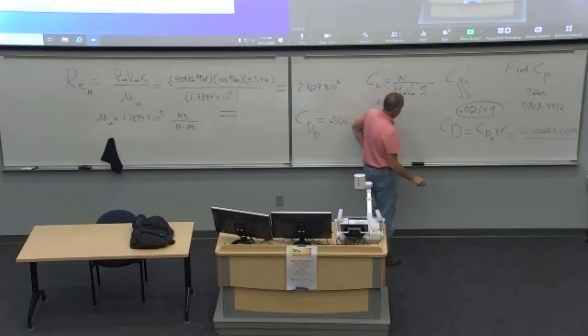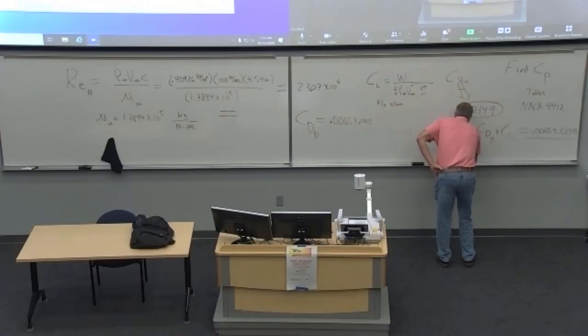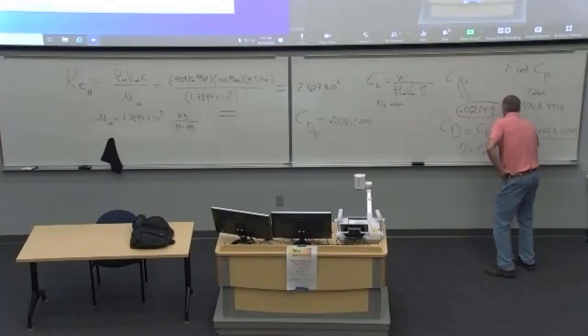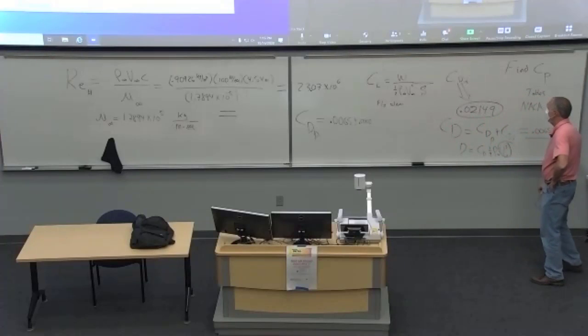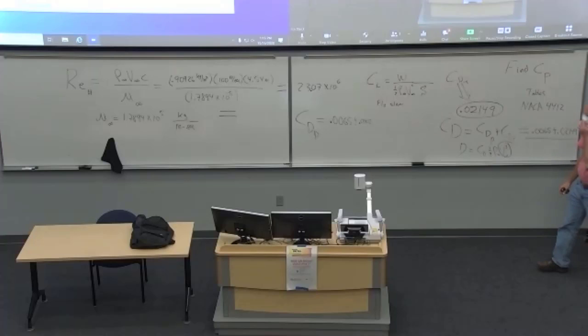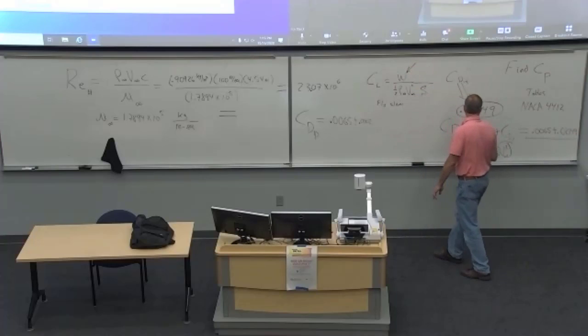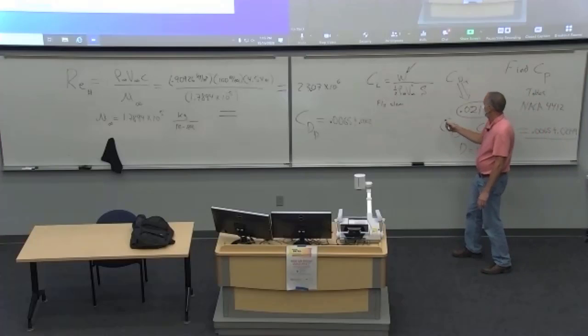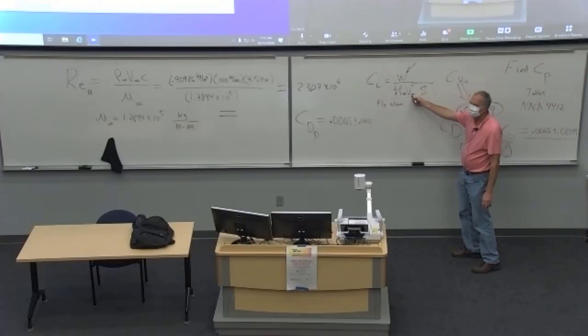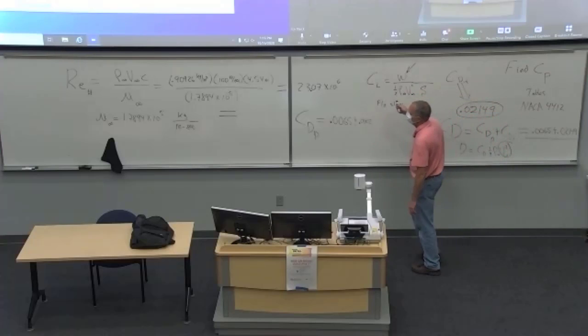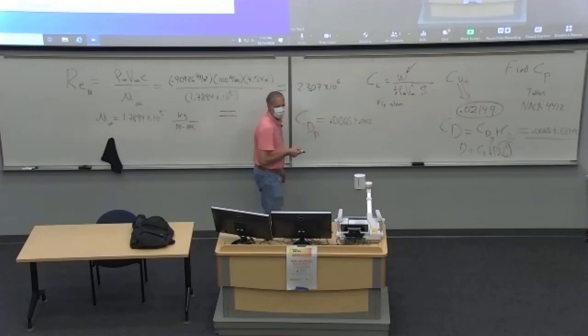And that would actually feed into the fact that we're going to have to multiply this. The total drag is CD times 1/2 rho V squared, right? So going to crank that up, but we still like to get CD down. What else could we do? Fly with less weight, because that's going to get us less CL. And notice, wow, there's suddenly a trade-off, because here's V squared that's going to make the drag bigger, and here's V squared that's going to make CL smaller, that's going to make CDi smaller, right?